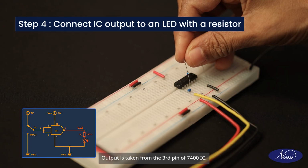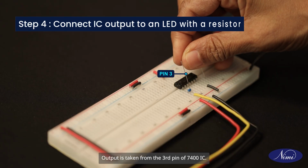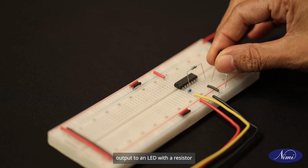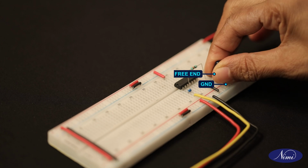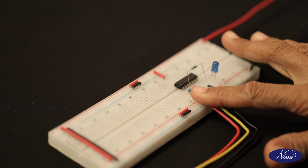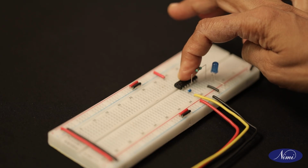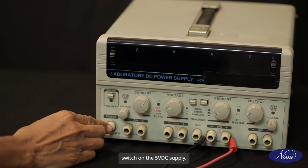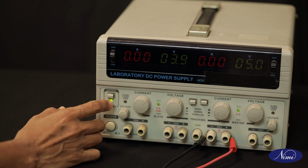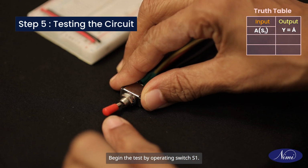Output is taken from the third pin of 7400 IC. Do not forget to connect IC output to an LED with a resistor. With everything checked, switch on the 5-volt DC supply. Begin the test by operating switch S1.